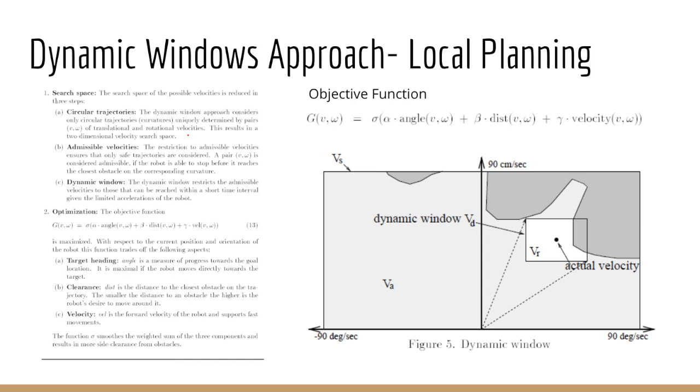This is ideal in our case as our robot needs to be able to react to unforeseen circumstances and changes to the environment. Most other planners respond poorly in this case if they're using a global planner. The dynamic window approach is designed to deal with motion dynamics of synchro drive robots, which we will have to change for our implementation since we'll probably model our car with a bicycle model. By searching in only the dynamic window, we make this a local problem and not a global problem.